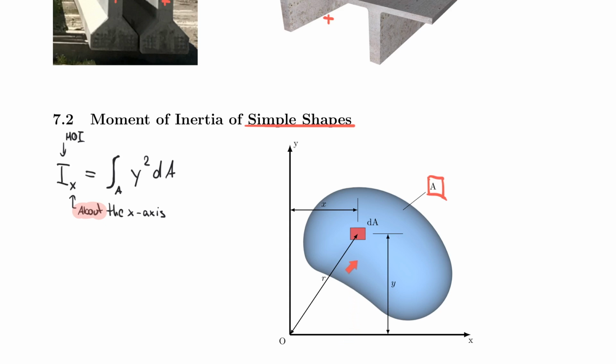So that is how the potato chip rotates about the x-axis, and for that to happen, you need to have the distance y. And it's very confusing for beginners to have the moment of inertia about the x-axis and then see a y in this equation. But you can probably now, with the help of this picture, understand where that is coming from.